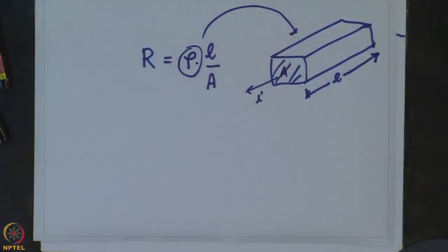One of the properties we look for in resistors is that their resistance does not change significantly with temperature. Okay. They have good noise characteristics and a good voltage rating. So basically, when we use a material in a resistor, its dielectric strength should be enough that it does not break down when we apply the voltage that needs to be applied to a given circuit. So basically these are some of the trade offs when we use these different resistors. Now I will just show you some pictures.